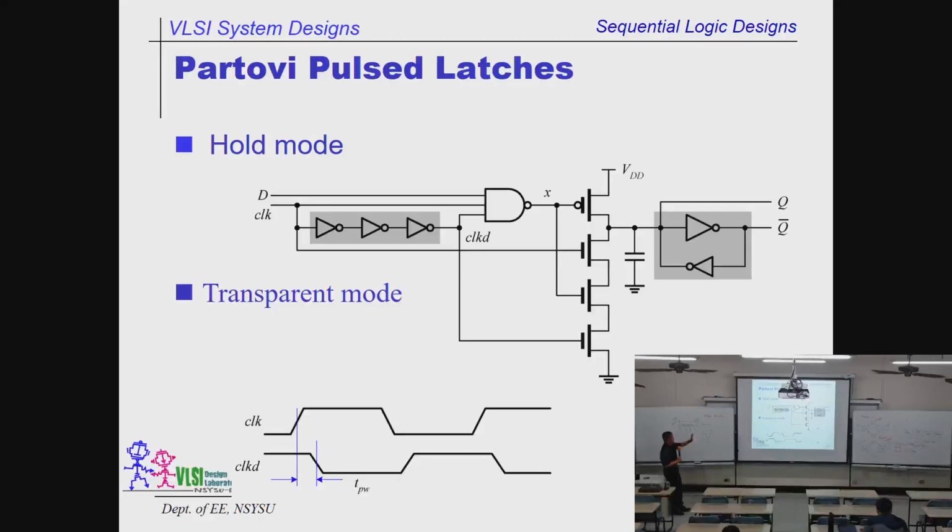You see, whenever you see a pulse latch, you always see an edge detector. Do you see the one over there on the top? It is another type of edge detector. The D goes with the edge detector, or the so-called clock chopper.